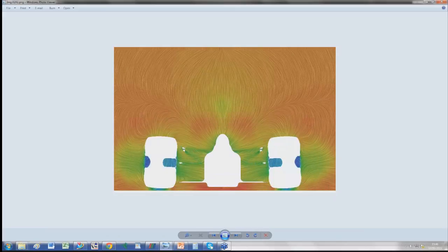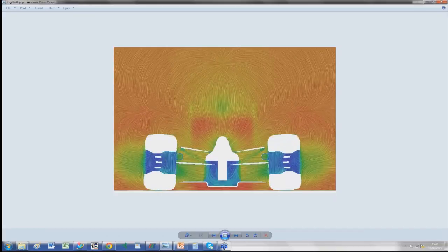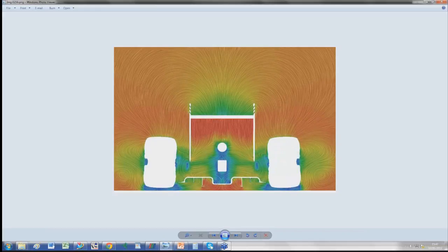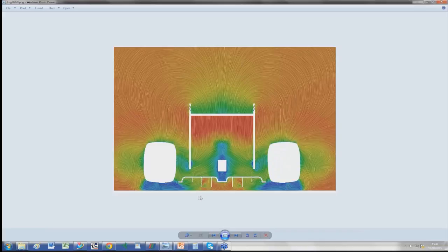We're closing towards the diffuser area, and one of the features in the diffuser is all these fences, vertical fences. They cannot be anything else than vertical by regulation, but you can give them the profile you want in plan view. And you can see, again, small vortices forming on the edge of them. What you try to achieve is to make them work very well, so you want to align them to the flow and give them the angle of attack they need, so they create vortices of the right magnitude.